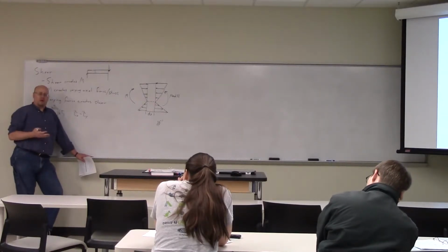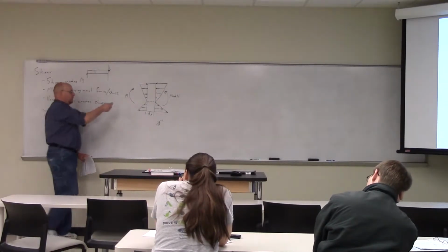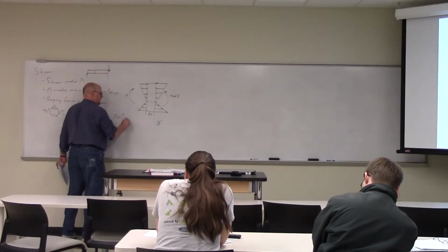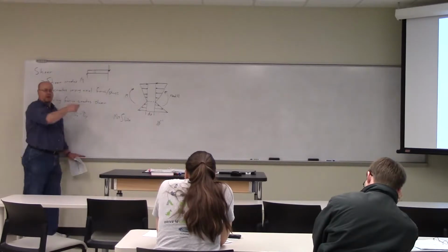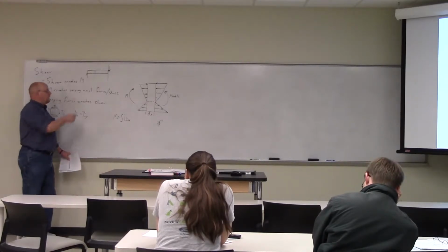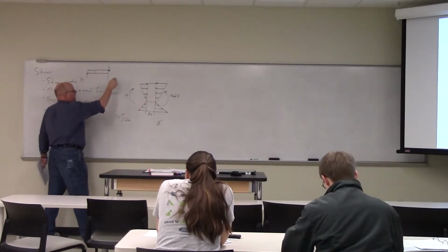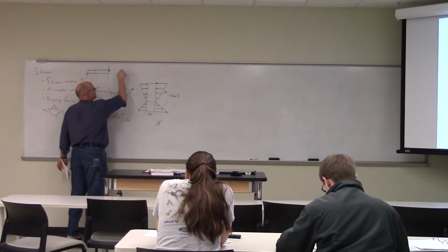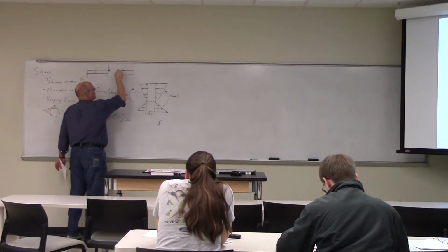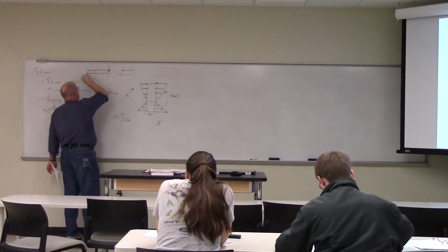I do a shear moment diagram, right? The moment here, M, is the integral of V dx as I move along that thing. It's the area under the V(x) curve. Well, the V(x) curve, if you think about it, is this, with some V, whatever's applied.